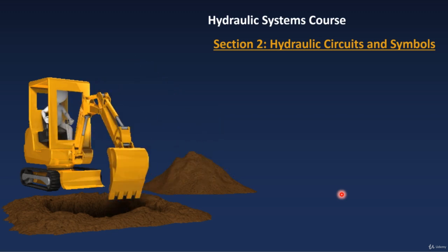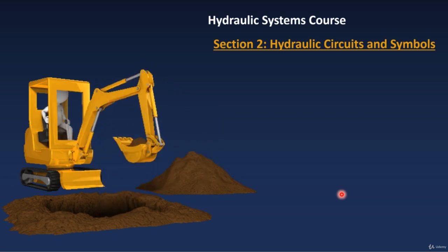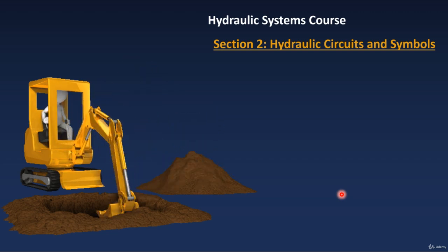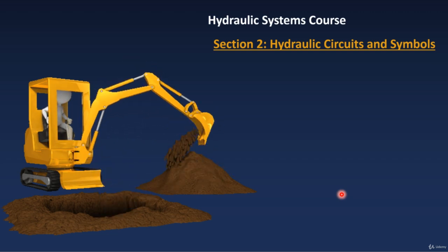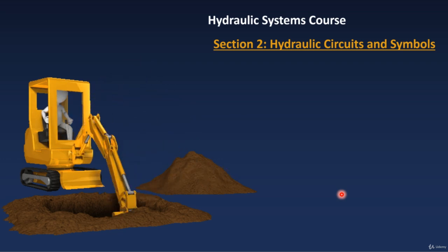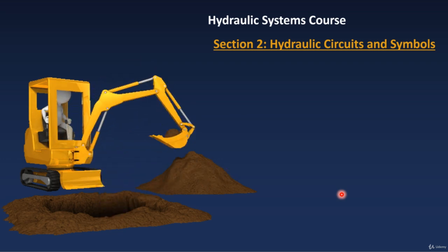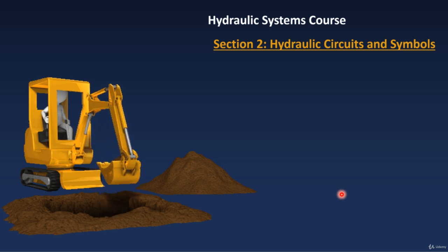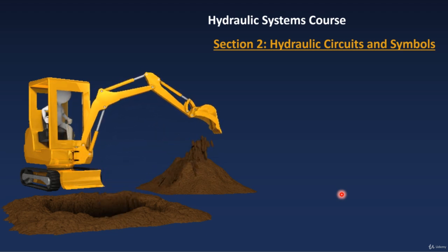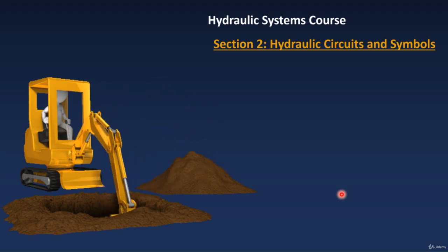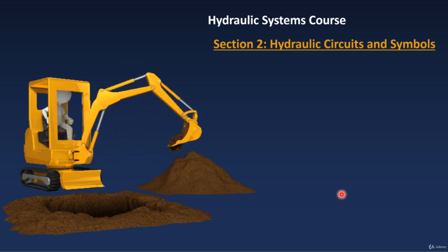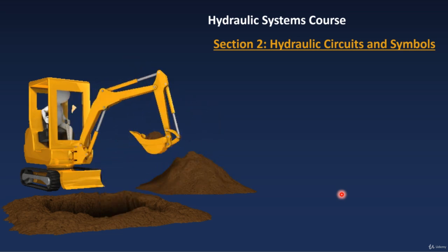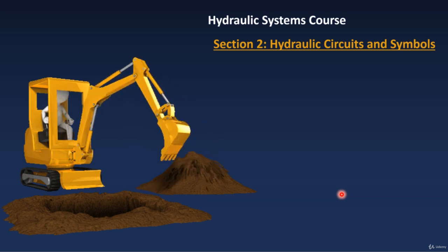Welcome back. In the previous lecture, we talked about the valve actuator symbols, which give me clear information about how the valve will operate. And we started talking about hydraulic cylinders or actuator symbols. We specifically talked about the single acting hydraulic cylinders. We understood the mode of operation and how the force created by applying pressure on the piston area will lead to a movement of the hydraulic cylinder piston to a certain distance.